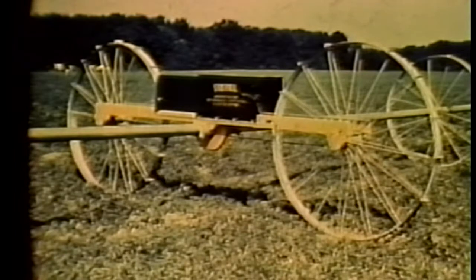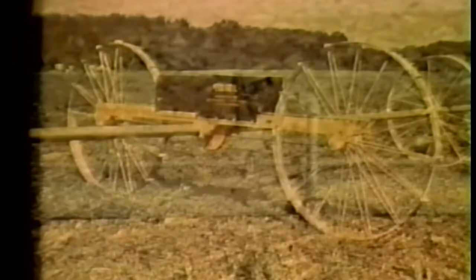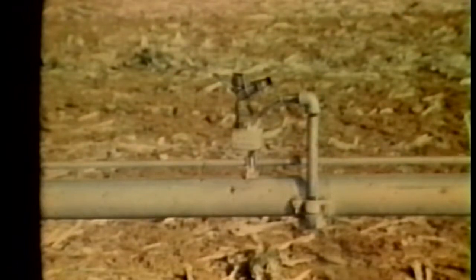When irrigating, the lateral remains in one place until the amount of water needed has been applied. Then the lateral is moved by an air-cooled gasoline engine supplying power to the drive train. Most engines are located in the center of the lateral line. Self-aligning sprinklers are used on a side wheel roll lateral. As the lateral turns, the sprinkler support pipe rotates about the swivel joint, keeping the sprinkler upright.